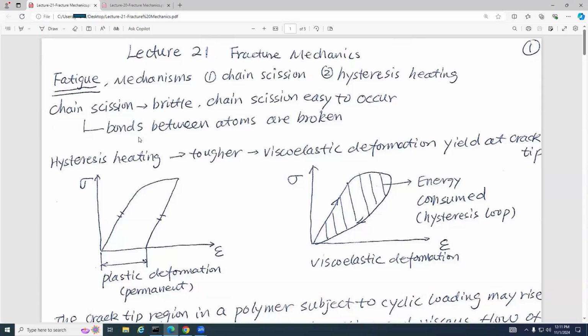Plastic deformation: last time I showed you this sigma-epsilon diagram. We go up along the linear elastic region, and after the yield point this increases slowly. This is still hardening, and you can see why it's called hardening: the yield strength is improving.